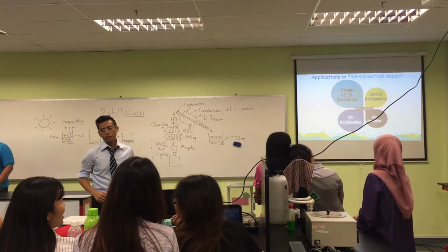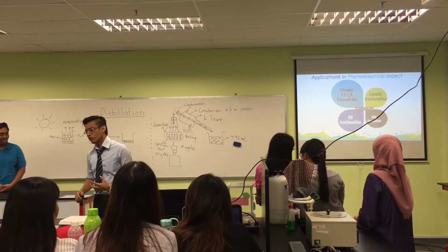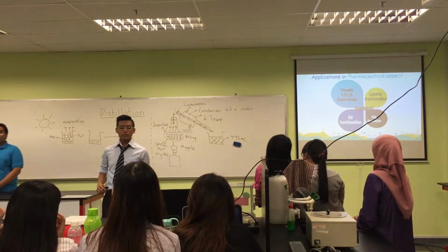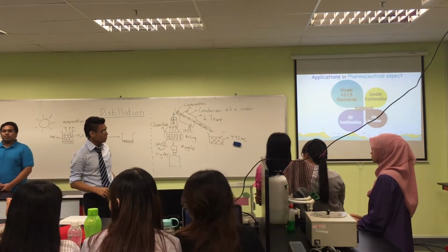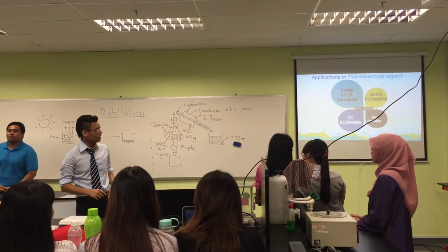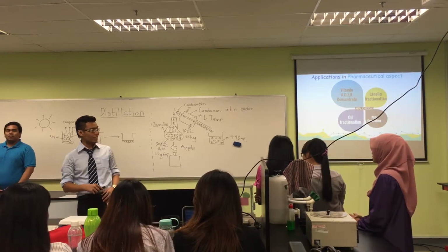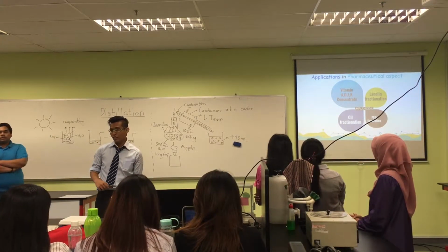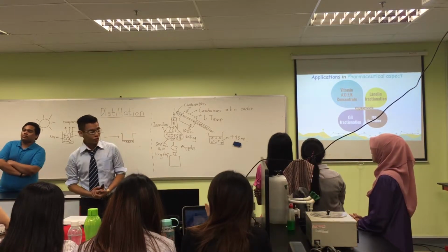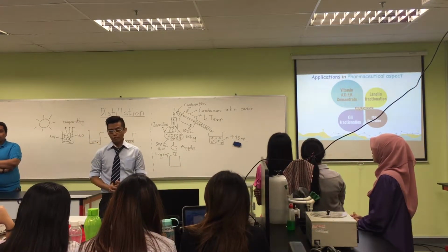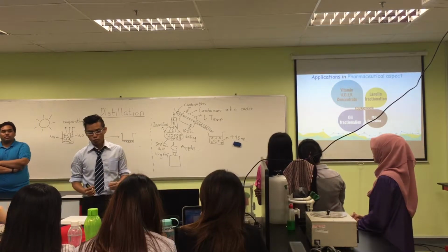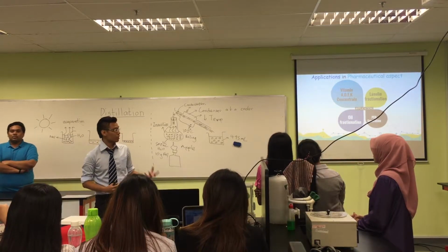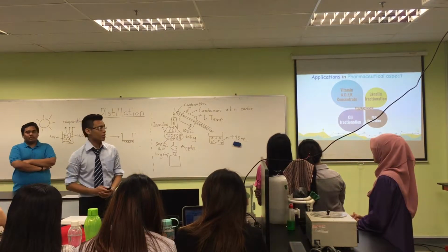First, we're using vacuum distillation. As we all know, we can boil some substances under their boiling point. So this is quite important. Firstly, in the processing of vitamin A, E, and K concentrate. For example, you want to boil fish oil and extract all the essential vitamins, and then mix them with other substances. So we need this type of vacuum distillation.